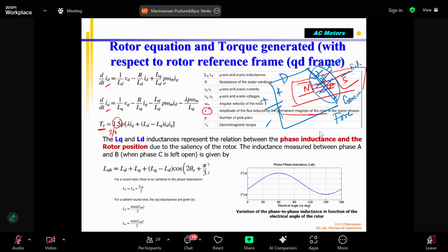Since the stator or field, the permanent magnet, is in the body, the coil is not moving. The wire which is attached in the rotor or armature is allowed to rotate. So the force is able to make the rotor rotate, and the actual force is generated by the interaction between the magnetic field from the current flowing in the coil, or armature or rotor coil, and the stator magnetic field. So, this is how this works.